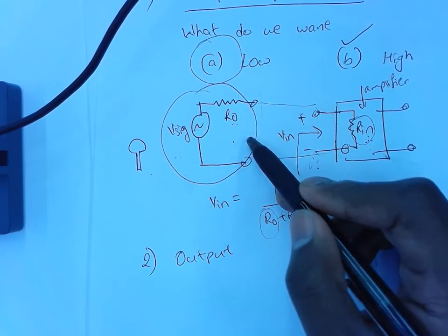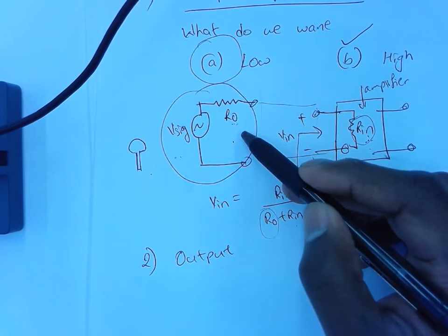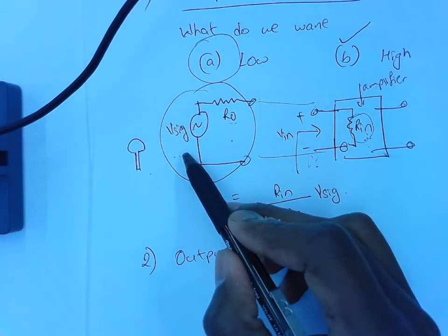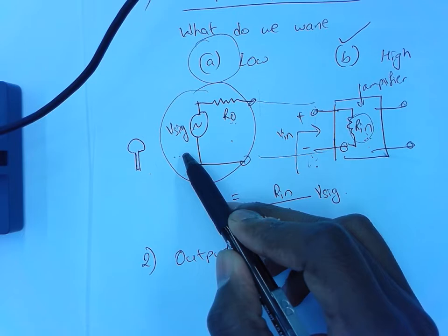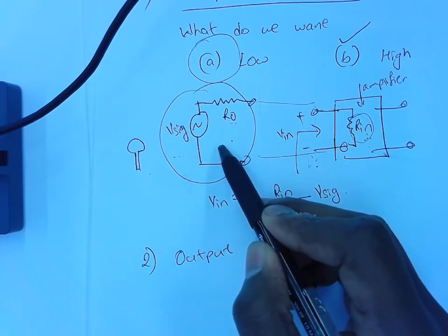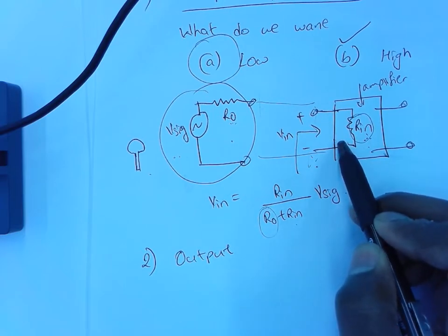If you try to draw any current from it, your signal is gone inside the output impedance itself. That's not how a microphone actually works, but you can model it this way. Usually your signal sources, which are sensors, if they're passive sensors, have very high output impedance because they cannot produce any output power. You cannot draw much current from it. That is why you want your amplifiers to have very high input impedance, so that you don't draw much current from it.